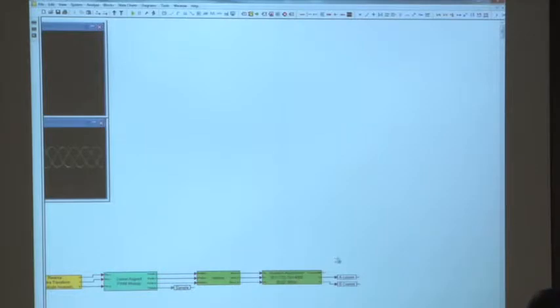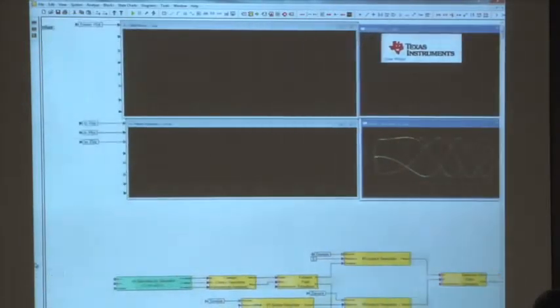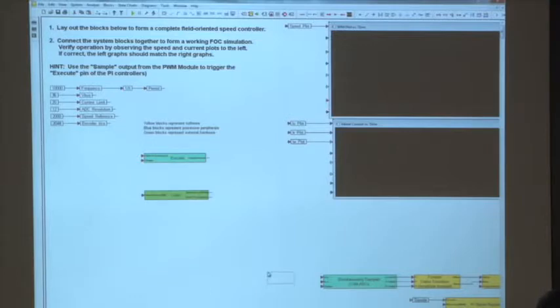Now, I'm going to take those 2 currents, click and drag over both of them to select them, hit Control-C, Control-V. And where do you think these are going to go? That's right. They're going to go back on the inputs of our ADC, for IU in and IV in. I shouldn't have labeled it that because that could be confusing. Just remember, if you did the same labeling that I did, A current goes into IU, B current goes into IV.